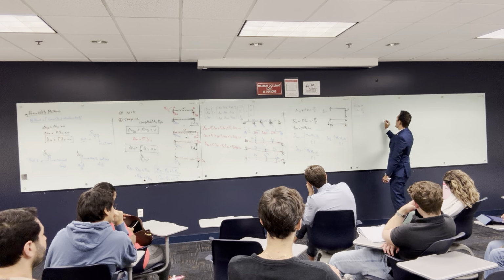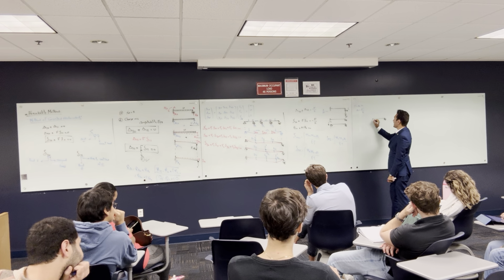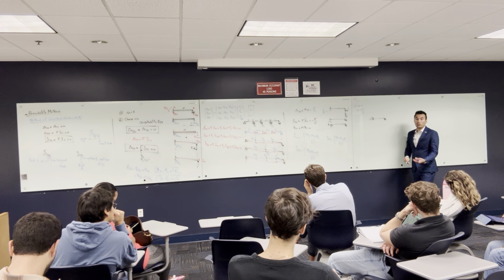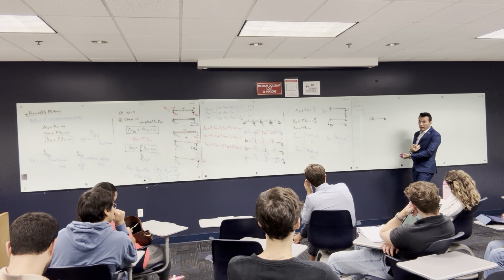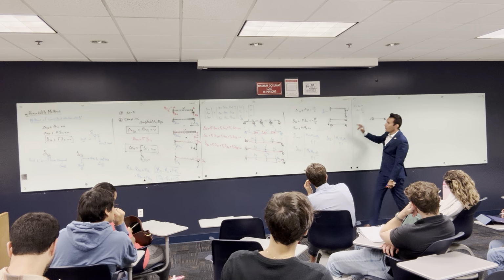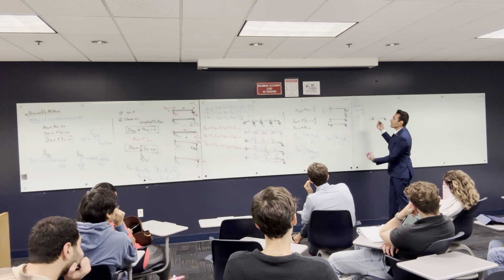But what if the same problem I made like this? I have a roller, and rather than giving you a fixed support, I'm giving you a rotational spring. The rotational spring, you can't remove it, because here theta is not equal to 0 anymore. So it is the same concept.